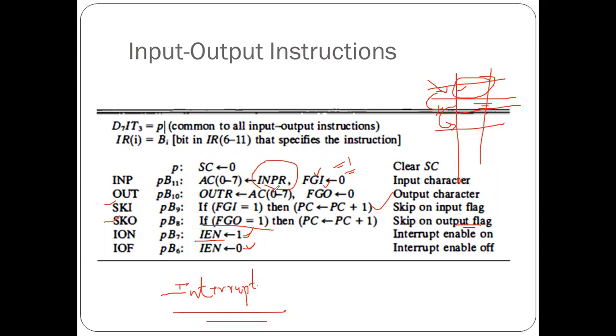After all the bits of a character are transferred to the output device, and printing has happened if it is a printer, the output register is empty, and that emptiness is indicated to the CPU by setting the output flag to 1. Whenever the output flag is 1, the CPU performs the write operation, writing the next character onto the output register with the help of the accumulator.